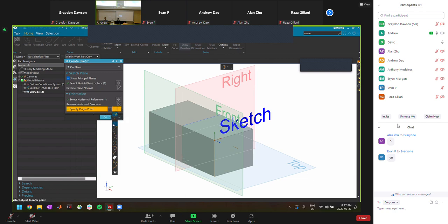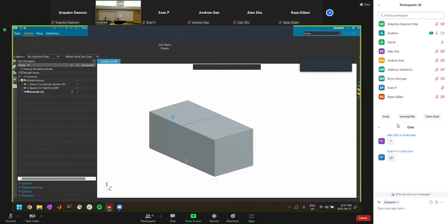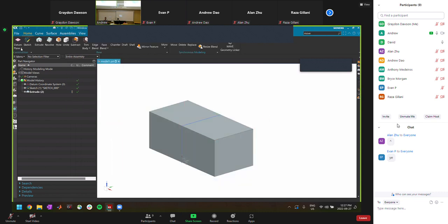Yeah, in NX, there's the origin, which has your X, Y, and Z. You can also set what's called a CSYS or something like that, which is another origin, but you can place it wherever you want. You can place as many as you want. So let's say you need an origin that's lined up weird somewhere, you can put a 3-axis origin anywhere on your part.